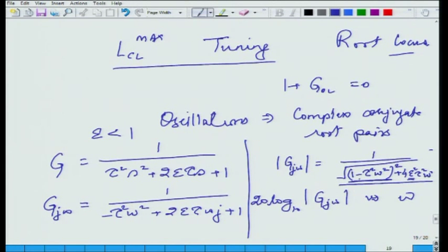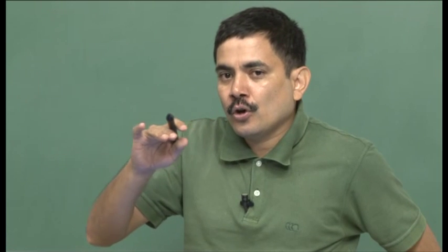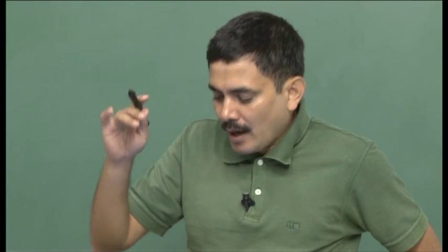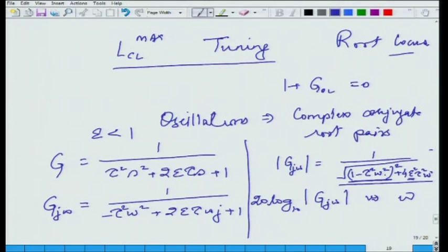and because the positive term is becoming much smaller, then what you will have is essentially this term is negligible, the second term is negligible as omega is increasing slightly above 0, the first term has become less than 1. If the first term has become less than 1, 1 over square root of that will become greater than 1, and therefore, your log modulus will become slightly above 0. However, as omega is increased further, of course, the second term will start to blow up, and then the magnitude amplitude ratio will again go down. So, you see that there is a hump that comes in the magnitude.